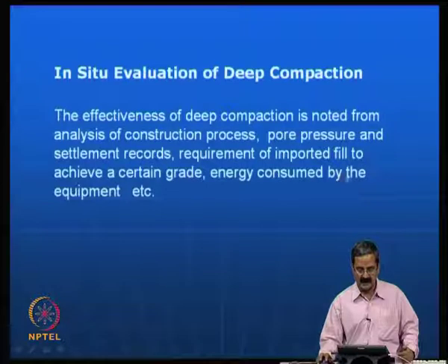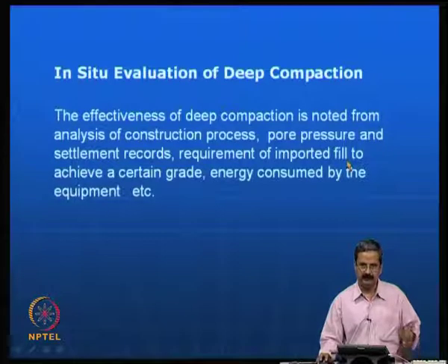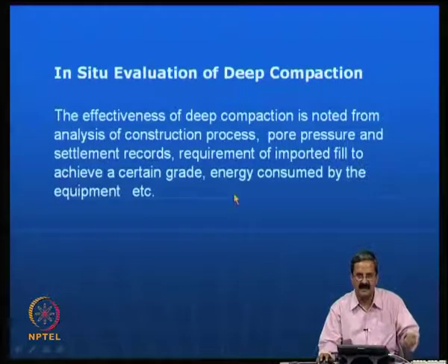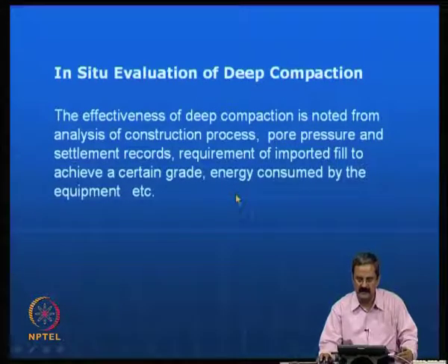So, in this process, you have to really check if the imported soil has the required properties, like whether it has achieved that density or water content and all that. Then another variable is the energy consumed by the equipment itself. The energy that you put into the soil system has a very good influence. The higher the energy transferred to the in situ system, the more efficient is the process of compaction.